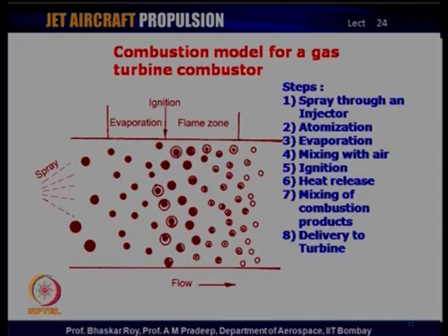It is necessary that these combustion products mix very uniformly throughout the body of the combustion chamber, so that they carry the heat uniformly over the entire space given to the combustion chamber. And once this uniform mixing has been achieved and the flow has been diluted by cold air, it is time to deliver it to the turbine.